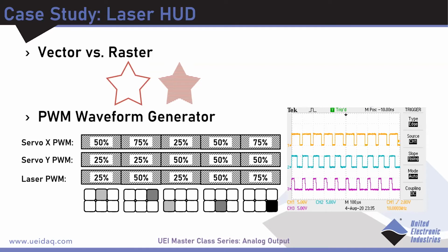So as you can see, all I needed to do to generate these PWM waves was simply input the duty cycle and set it to run. There wasn't anything very difficult about timing it correctly. I simply needed to provide the parameters my application required, and I could get this output. And of course, you can dynamically change the duty cycle as your PWM application needs.